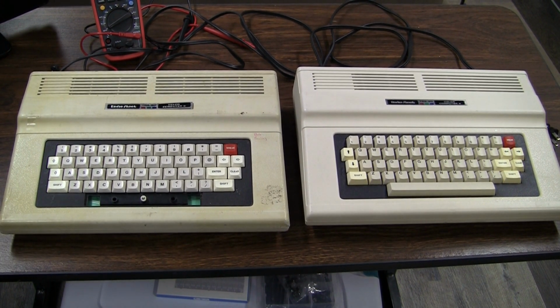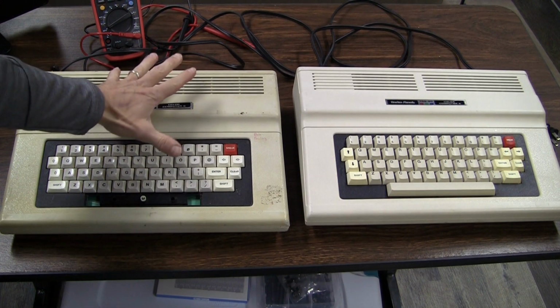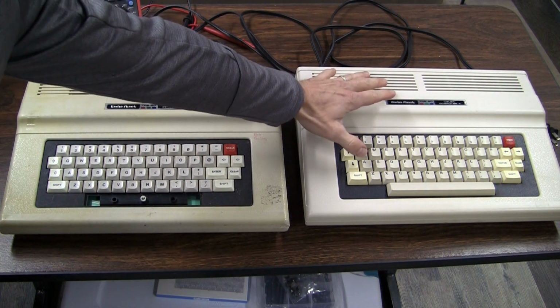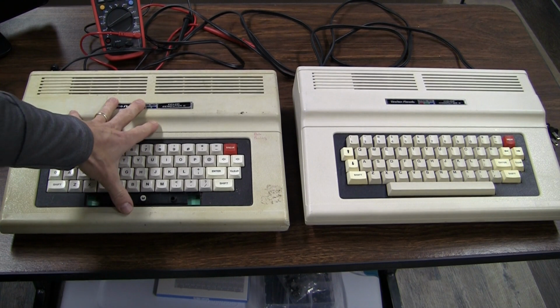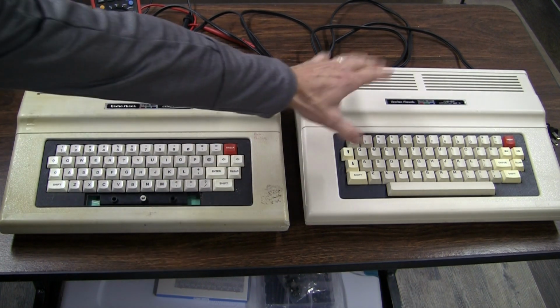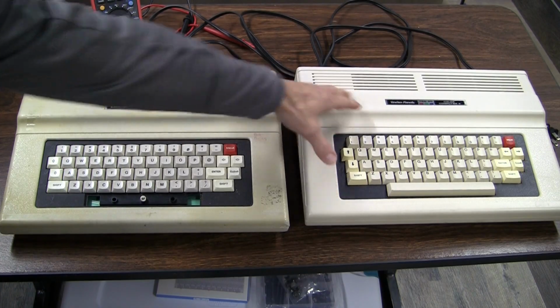So these two computers are going to be modded today. This is my oldest one, and this is my middle one as far as serial number and age. So this computer is going to get a composite video output, and this one's going to get composite and S-Video. Fortunately, no matter which version of the CoCo 2 you have, all the mods that I'm going to show you today will work on any of them. I'm just choosing to do only composite on the old one, just as a matter of choice, and making composite and S-Video on the middle one. But you can do anything that you'd like, and there are a lot of options, as you'll see in just a minute.